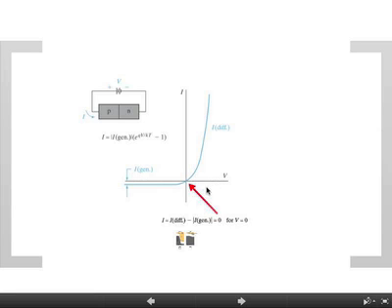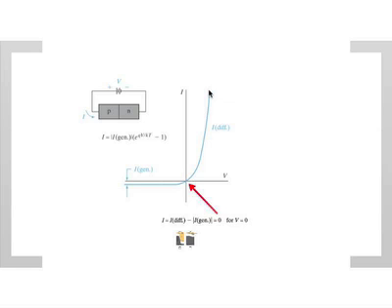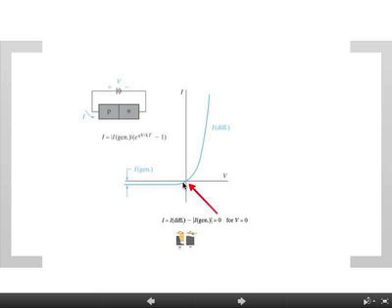Okay, when the voltage is positive, the current is high, it increases. It's pretty much like an ideal diode, except that it increases. And when the voltage is negative, the current is essentially zero. There's a small negative value, which, of course, we now know is the drift current.